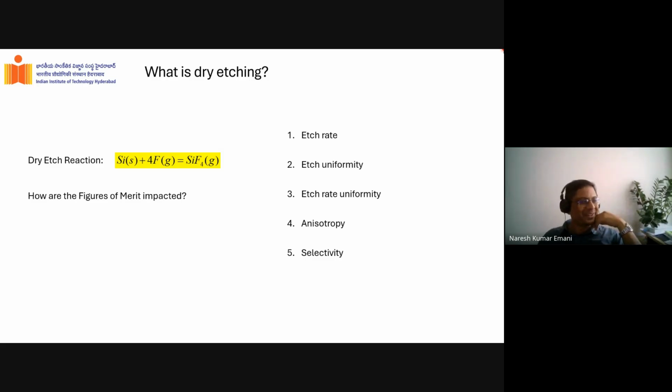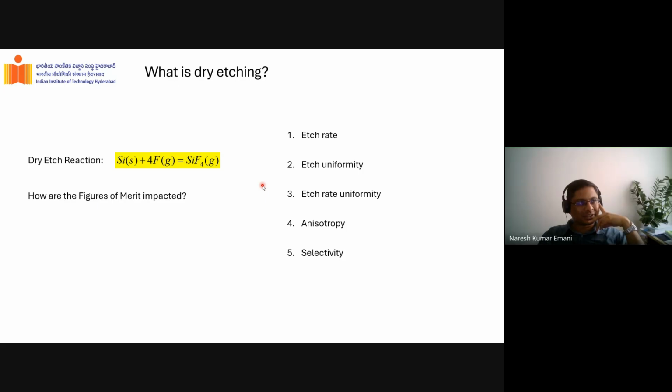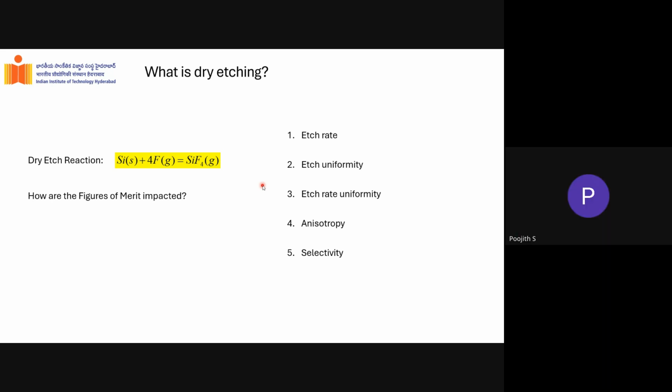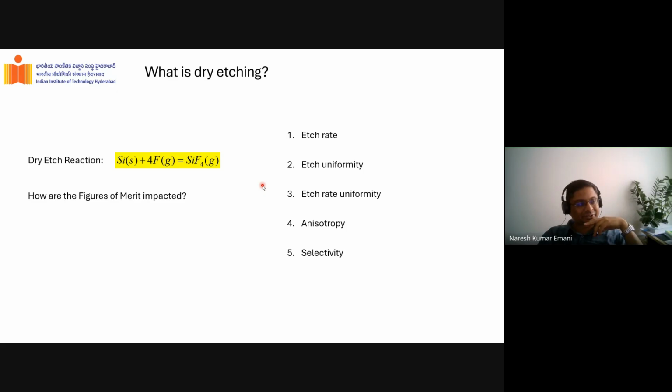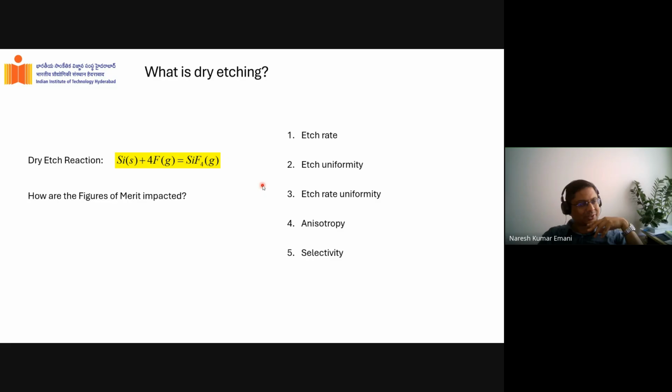Right? How do you make it anisotropic? Control the reaction rate with some energy. How do I control the reaction rate with energy? By reducing the randomness of the gas. Very nice. How do I reduce the randomness in the gas? Focusing it like a beam. Adya, control the speed of the flow of the gas. But is the problem the speed of flow of gas?